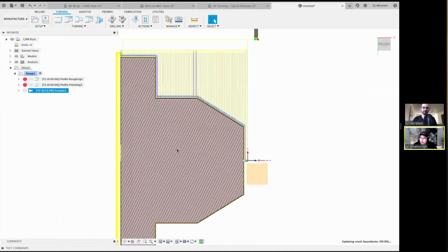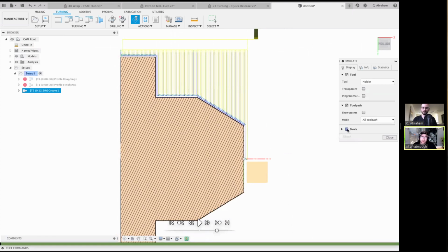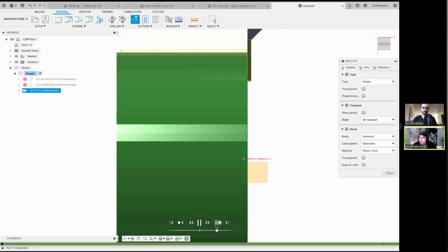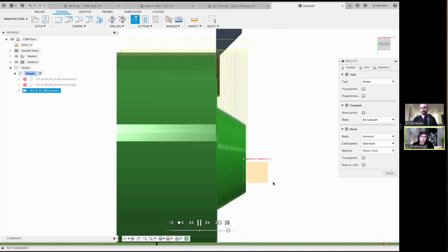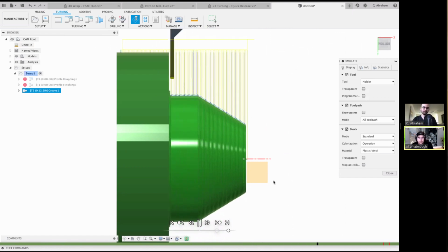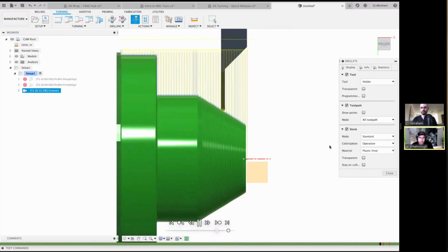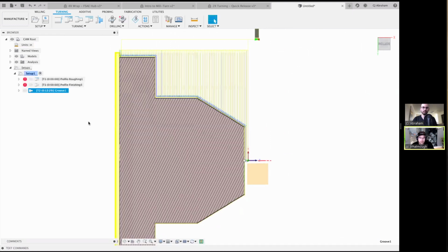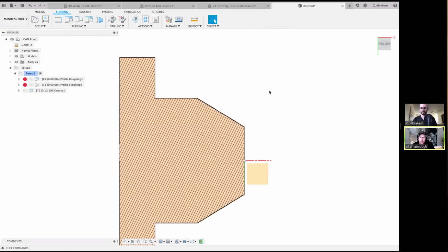And I think the additional thing is, in some cases or other systems, you might say, I'm going to go plus 1/4 inch, but then later your change might be that I'm changing from my datum being at the front of my material to being at the back of my material, at the face of the chuck. The intent of moving past the front of the model by the thickness of the tool means you can make a bunch of different changes and your intent is preserved.